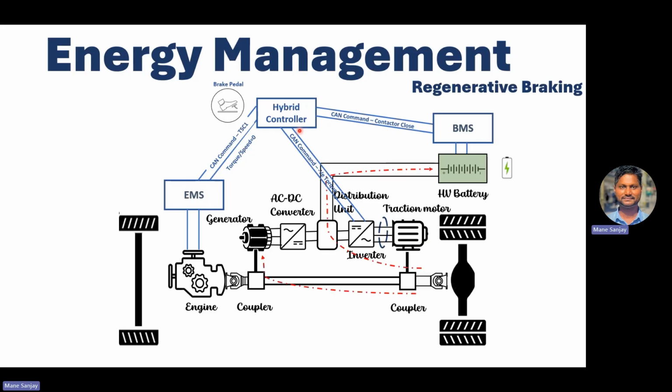You can get it more precisely over CAN, and that information the hybrid controller reads, and accordingly it sends this torque command, and you can effectively manage the regenerative braking operation. In ABS, it gets difficult, but if the ABS is there, still you can manage. But without EBS and ABS, it gets very difficult to put together your control strategy for how much braking effect is required.